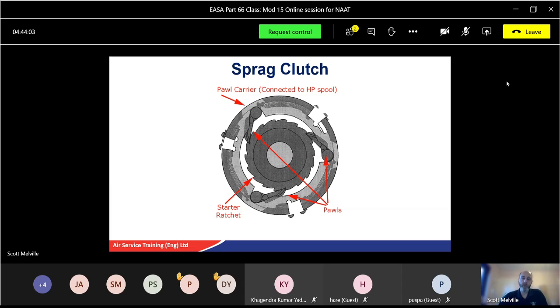Sprag clutch or support bearings where the drive sees that the engine would then drive the starter. Furthermore, the pressure regulating valve control fit may fail, with too much air over the top of the starter, so you need something to prevent this from causing excessive damage. You might have a mechanism that actually shears as well to stop that happening. Once you're under high torque, it's held apart by what's called a Belleville washer. The Belleville washer will over center and remain in the new position until reset manually, and that can only be done when it goes back to the manufacturer.